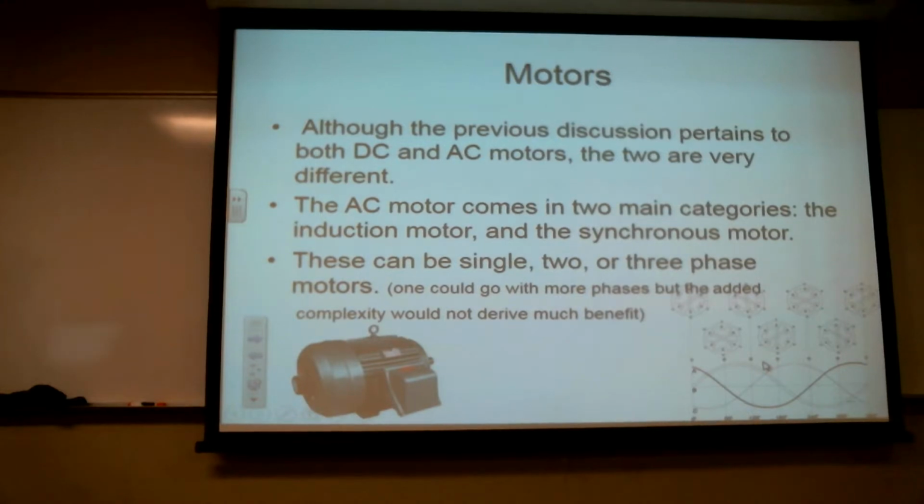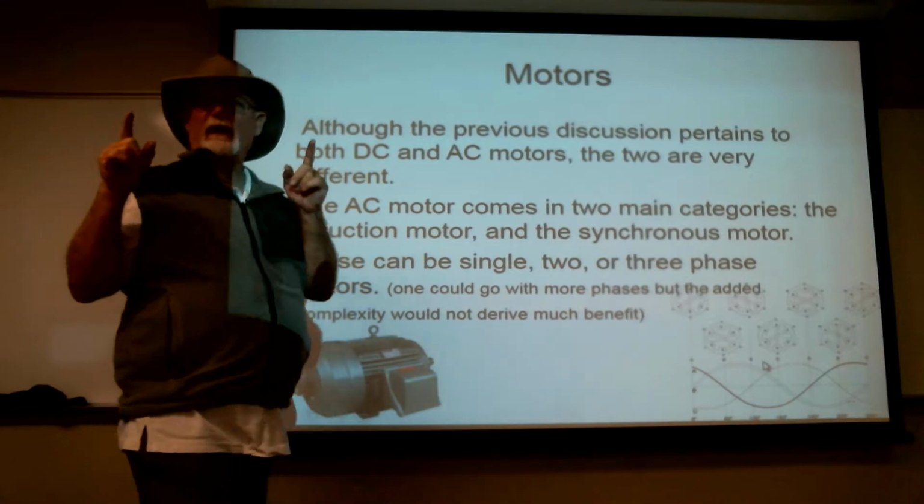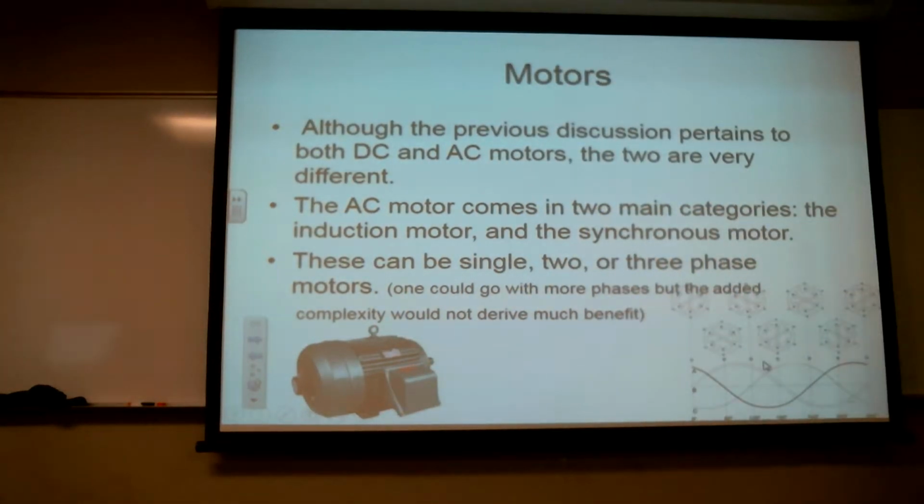Now, the other thing is, remember we said there was single phase and really 3-phase AC with 3 windings, so we can produce all 3 phases, or we could go between any 2 of the windings and have single phase, say 220, or we could go from the neutral across just one of the windings and have single phase 110, or 440, 220, whatever we ramped it up to.